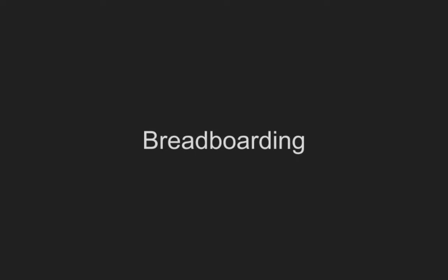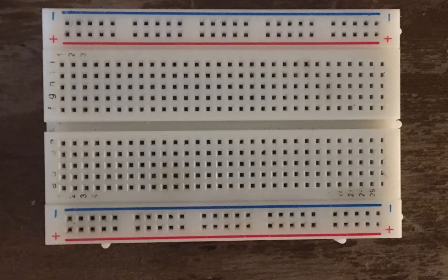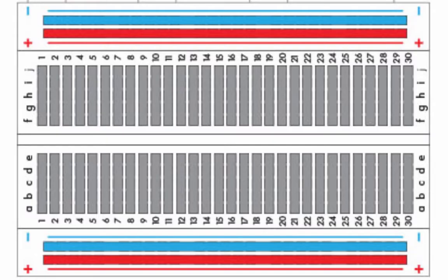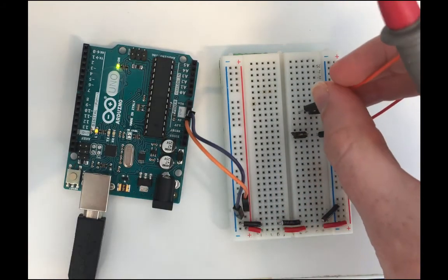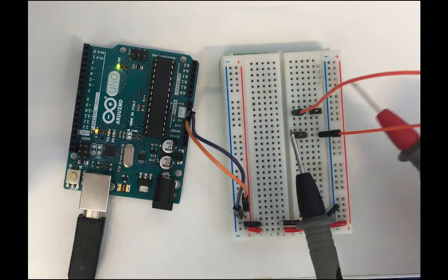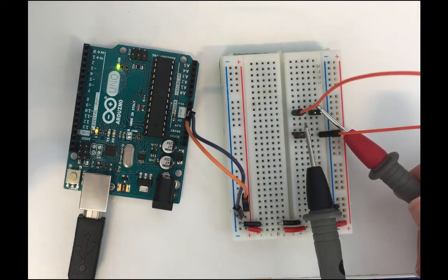The breadboard is a prototyping tool you can use with the Arduino. It is not necessary, but using it allows you to keep your circuit more organized and easy to understand, especially when lots of wires are involved. The breadboard contains metal strips that connect certain areas of the breadboard. As you can see on the multimeter, these are the connected bus strips. By connecting different areas of the board, the current is now going over both of these strips.